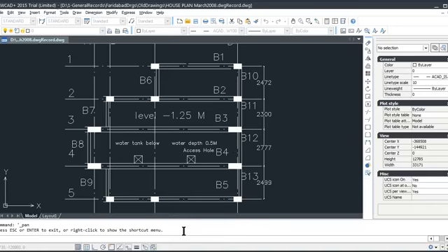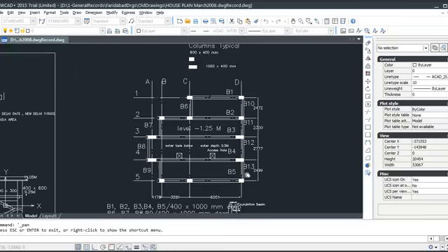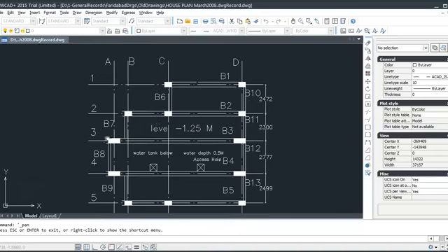And this is the same thing, means I calculated moments for this, and I found center of gravity of loads and center of gravity of building, and in plan where it is equal, I find x-axis, and then I found another axis where load line is. Similarly, I checked all that, how much out of line this load goes, because this is not symmetric, this is unsymmetric.